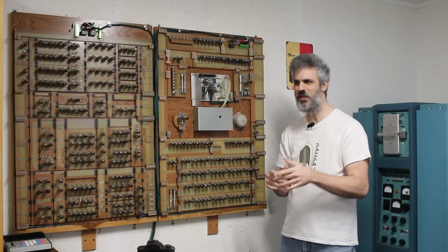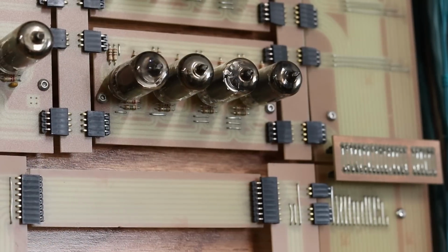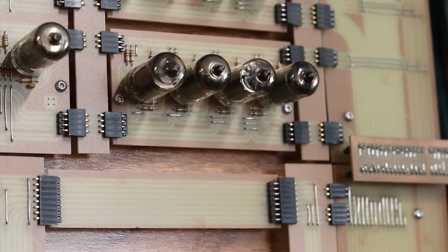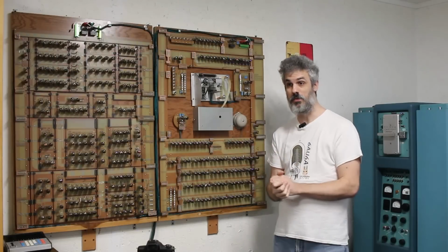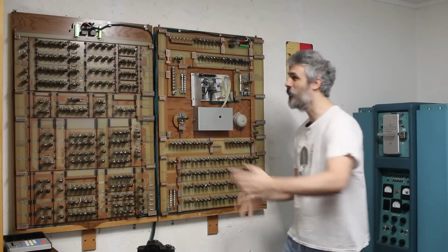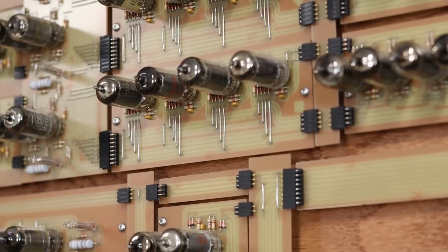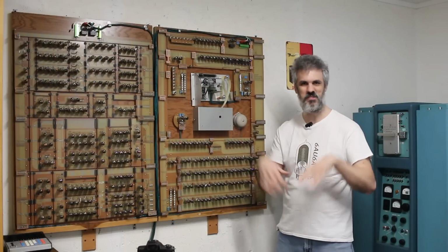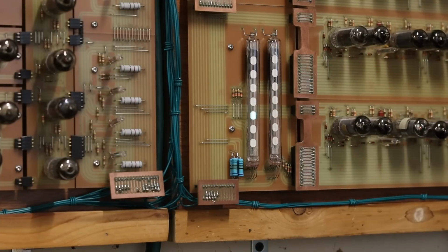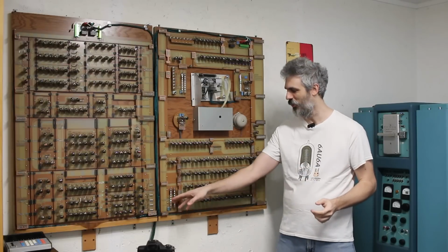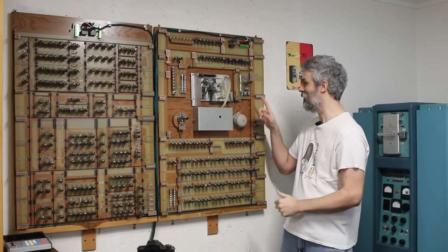The only thing that's really changed since the last time you guys saw it was that I swapped out some resistors in the buffer up here that drives the bell driver circuit to ring the bell. But that didn't solve the problem. The bell still just kicks off and goes absolutely bonkers all on its own. I think the problem is going to be somewhere here in the decoder, not in the buffer, but I'm going to have to dig into that a little later. So for now, the bell is unplugged and unpowered, so it's not going to ring the bell. But what we're hoping to see is 10101, which should equal 21 on our little output down here. I've never actually tried running this program in here, so let's just go for it.